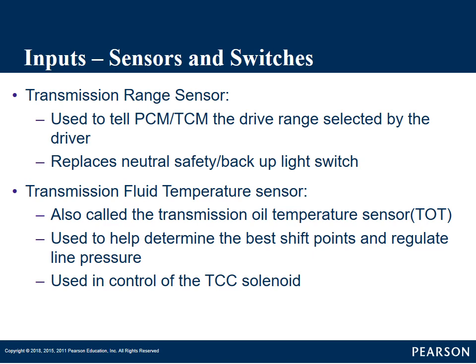Or our reverse light switch. In non-electronic transmissions, there was a separate switch that when you put it in reverse, it closed the circuit to turn your backup lights on. So people knew you were backing up. Okay. Now, on the vast majority of transmission range sensors, that's built into the sensor.